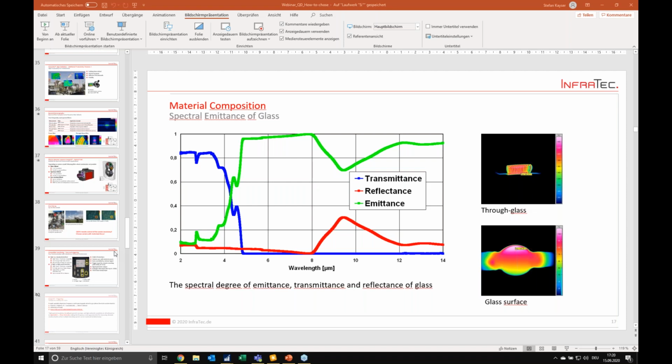And because you're measuring a sequence, you can apply a fast Fourier algorithm on this, and then simply magnify changes in these images. So this really edges out the performance of such a camera. These little temperature changes caused by the current normally are not visible with passive thermography, simply because these temperature changes are too little. But with the consequence of the fast Fourier analysis, you can highlight these elements.